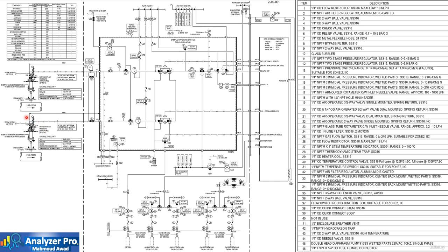In this example we noticed that the advanced reflux sample we discussed before is used to condition the sample at the sample tap point before it is transmitted through the sample line. Also, a sample pump is used to boost sample pressure to increase flow and provide good response time for analysis.